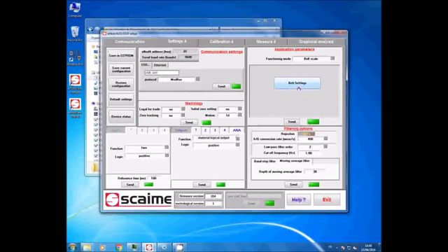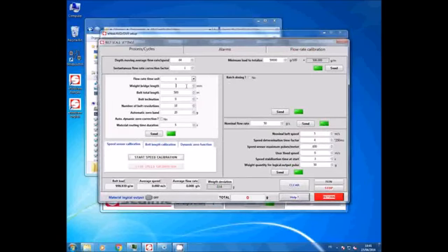We will now click on the parameter button. We can now set up our system: the belt length, the conveyor angle, the number of revolutions required to make the zero or to learn the belt length or the speed sensor, and finally the automatic correction 0.